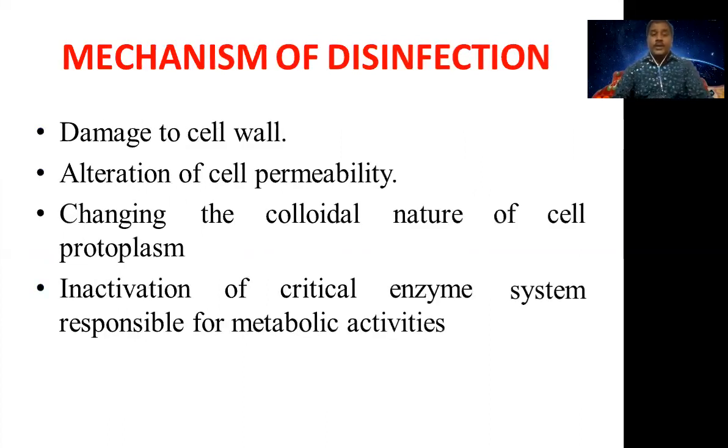Then what is the mechanism of disinfection? It damages the cell wall. Also, alteration of the cell permeability may take place, changing the colloidal nature of the cell protoplasm, and inactivation of the critical enzyme systems responsible for metabolic activities. These are the major mechanisms of disinfection.